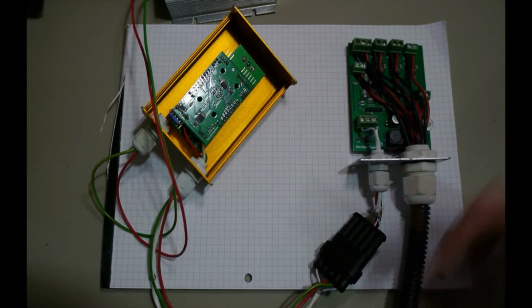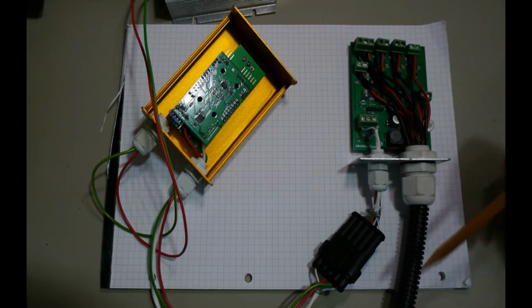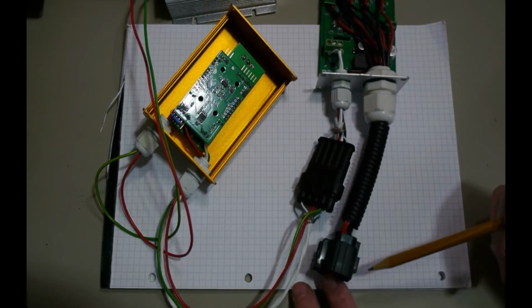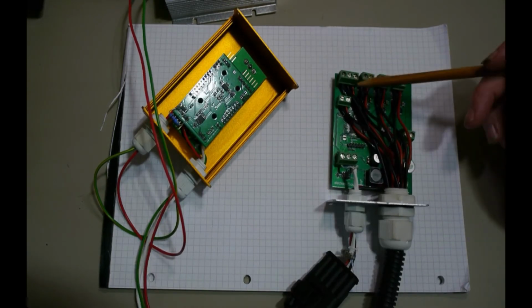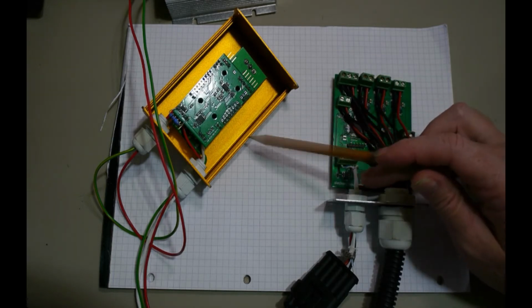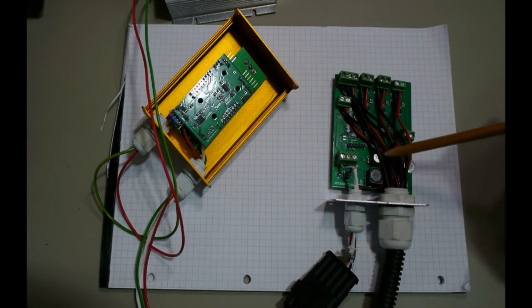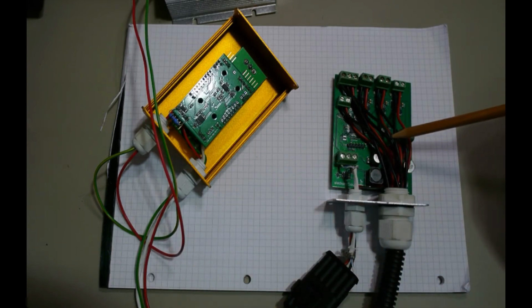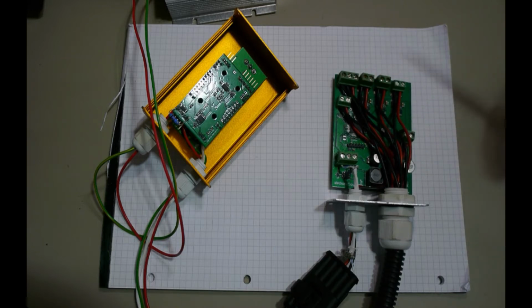So at the minute I was testing with this and I've connected up. This is the connector going to the mower and the mower's inputs and outputs, and they are connected through to the various connectors here. And so the human input device, or interface device, is going to send CAN frames down to this control box, which is then going to turn on 12-volt actuators, which are going to control the solenoids, which control the hydraulics. So that just leaves the code.